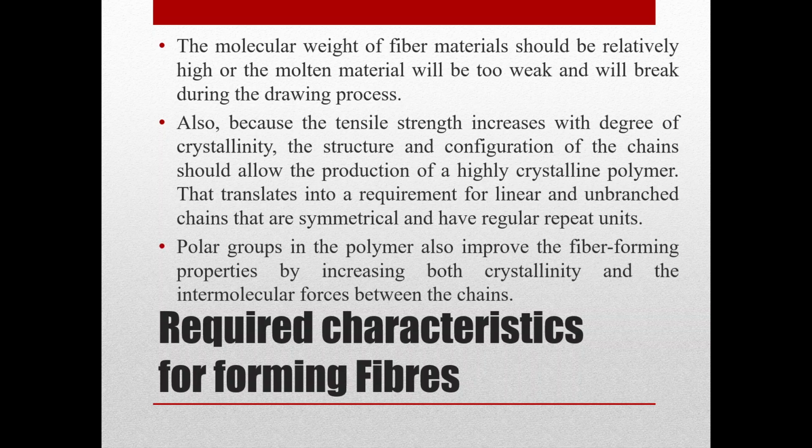That translates into a requirement for linear and unbranched chains that are symmetrical and have regular repeat units. Polar groups in the polymer also improve the fiber forming properties by increasing both crystallinity as well as the intermolecular forces between the chains.